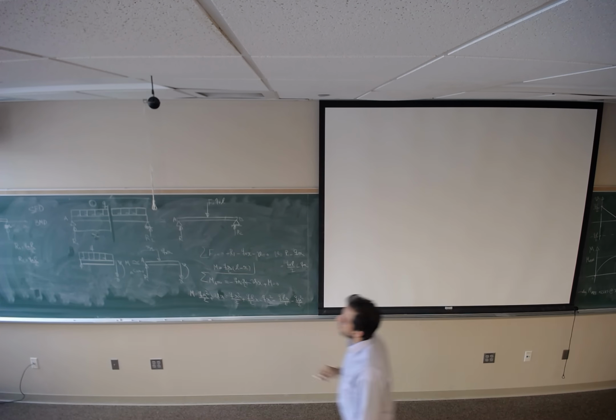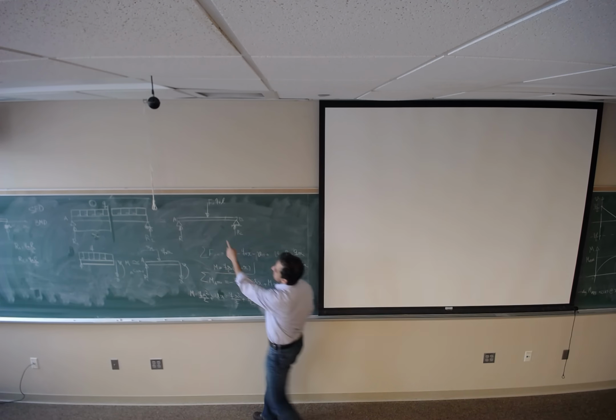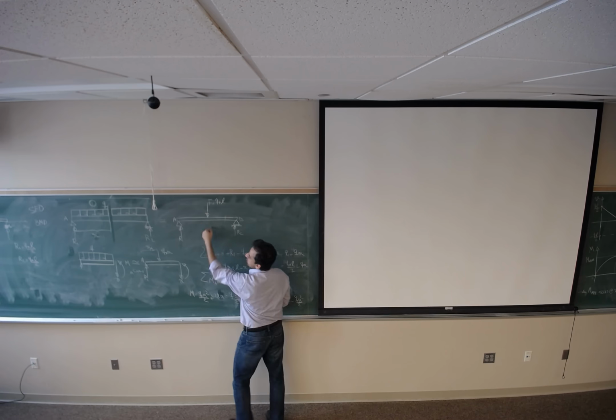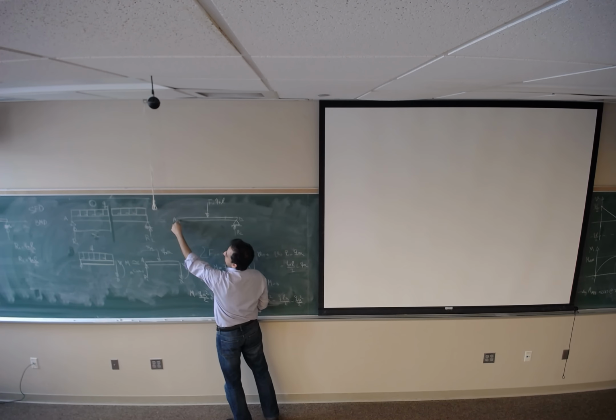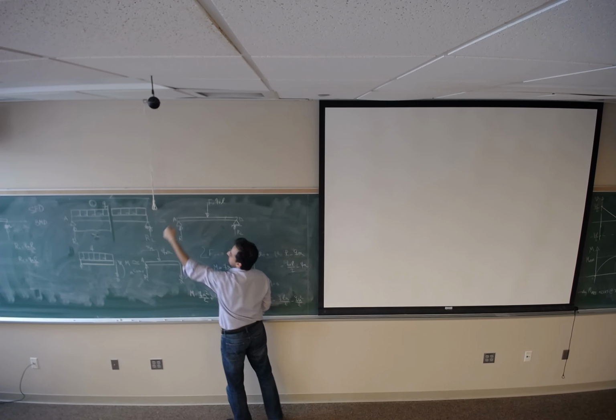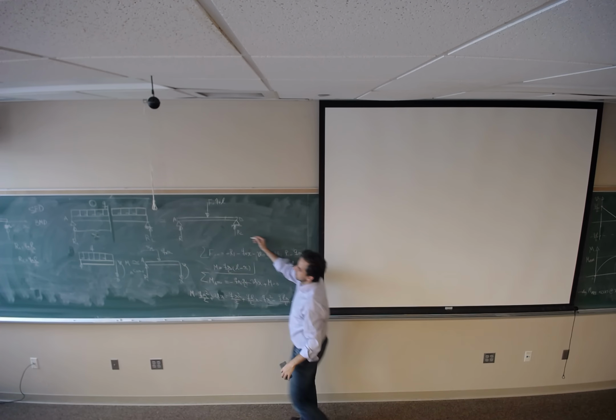If I ask you the direction of the bending moment, these forces are going to rotate the beam, making a moment about the axis coming out of the plane. So on the XY plane, we have M about the Z axis.